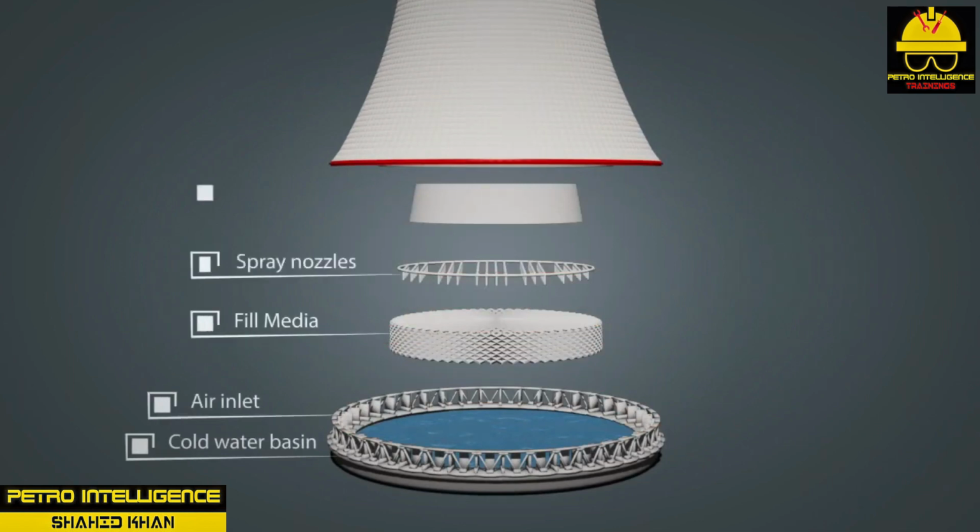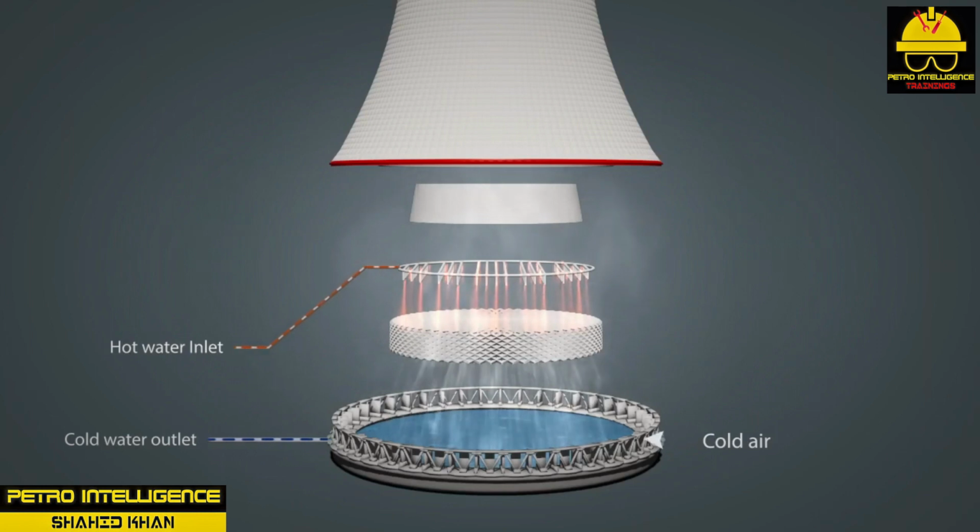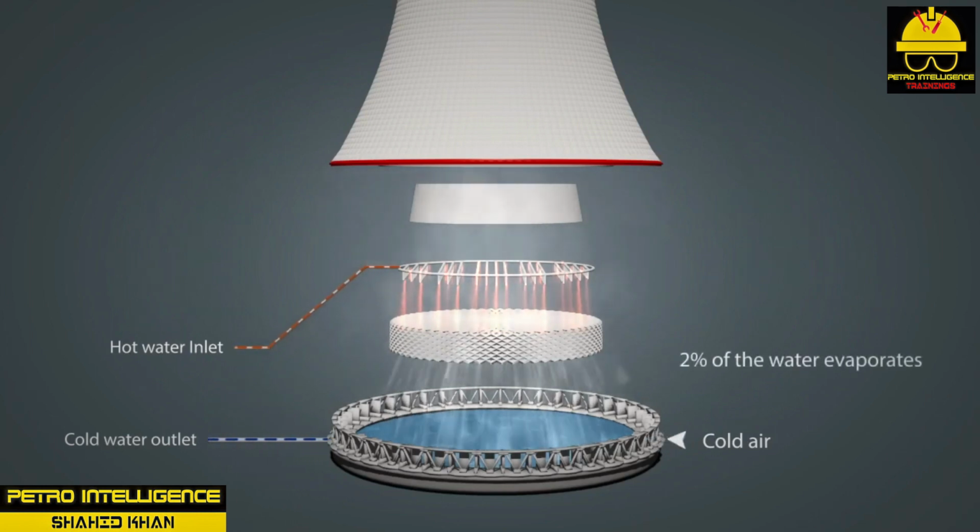This process results in both sensible heat loss and evaporation. Sensible heat is heat that can be measured or felt. When water changes to vapor, the vapor takes heat energy with it, leaving behind the cooler liquid. Evaporation, which accounts for 80 to 90% of the heat loss, is the most critical factor in cooling tower efficiency.